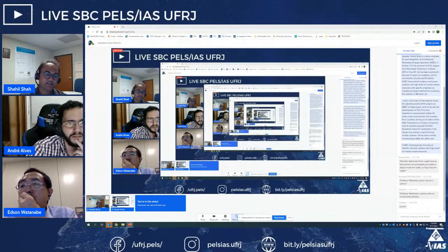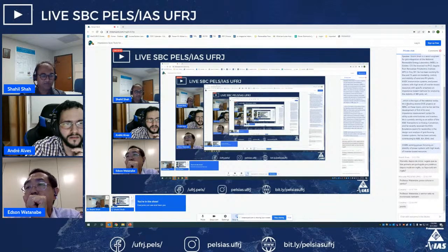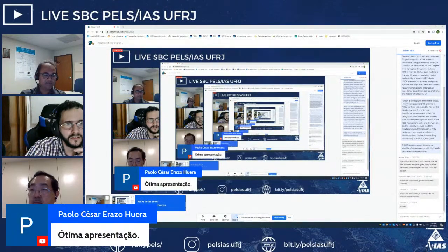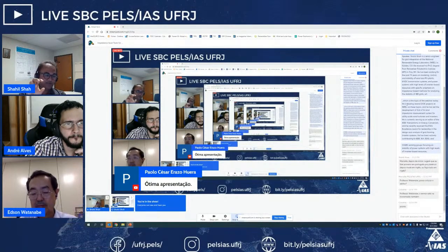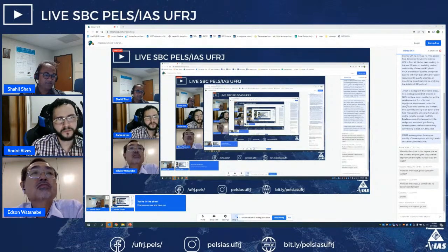So this is a small signal scan. We are injecting the disturbance at a really small scale. We are not dropping a big 100 megawatt load, or injecting disturbances which are really large. If you talk about the actual measurements that we do at NREL, our grid simulator in a way isolates the grid from all these experiments. And in the PSCAD software tool, where I use a yellow box between an IBR and the grid, the perturbations are small. As I said, we want to keep them small enough so that they don't excite any non-linearities, and so they are not going to basically create any instabilities.